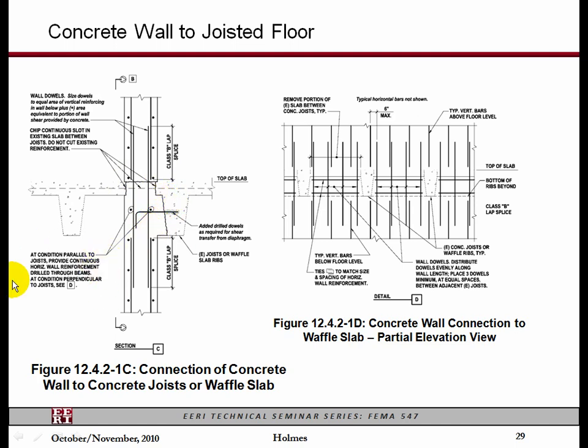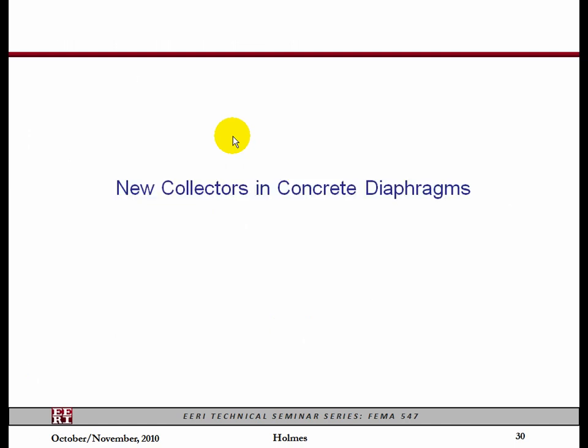So there's a bunch of suggestions here and things to watch out for in putting shear walls in, and again it points out that you might want to make these holes intermittent like this, so as to avoid the shoring that would be required if you put a continuous slot in.